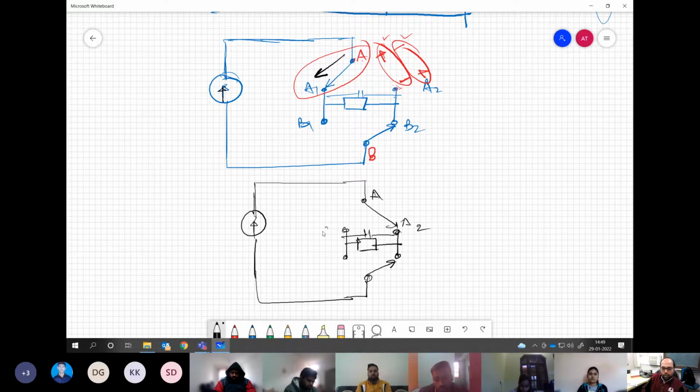This is connected over here. Now again, when you talk about this connection, from A to A2, the polarity of current is fixed. This cannot change because this is what the current source is giving. Whereas this voltage A to A1 is not defined. There is no stiff voltage source or anything which can define what the voltage is. So the polarity of the blocking voltage could be both, either this way or this way. You understand the point?